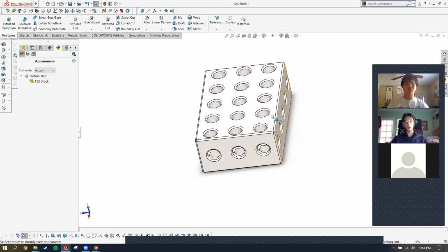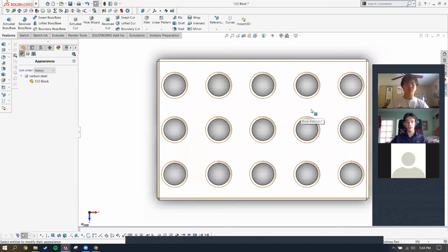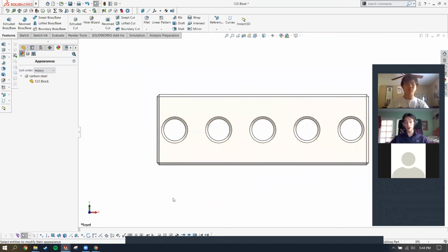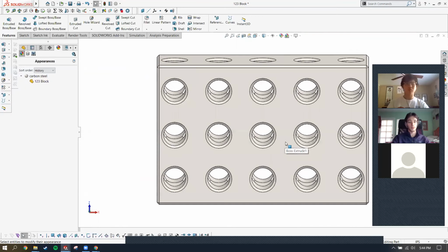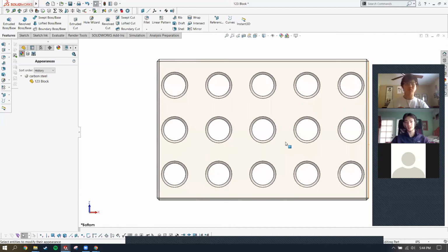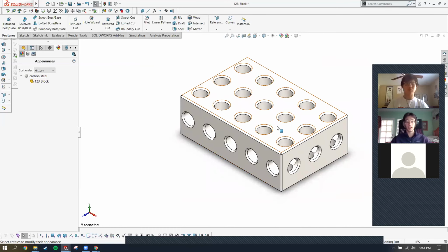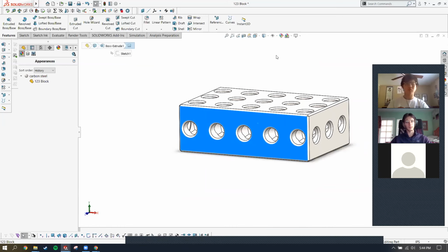If you hold Control and press the numbers 1 through 9, it'll take you to the standard views of the object. And if you are in a standard view, you can see on the bottom left here, beneath my axes, it says star front. It means I'm in the front view, or the back view, left view. And up through 6 are the 6 standard face views. And then 7 is the isometric, 8 is the front, and 9 is the normal to view, I believe.